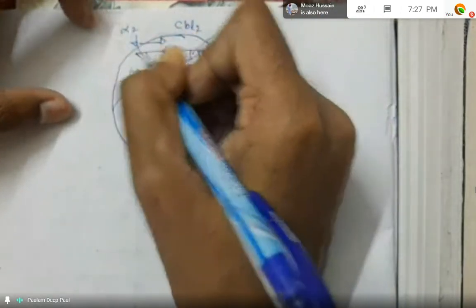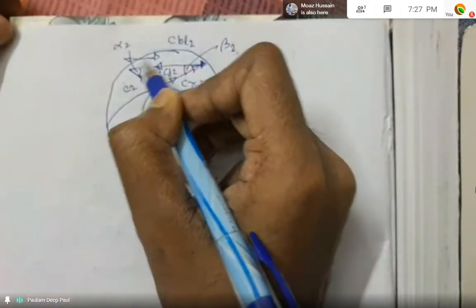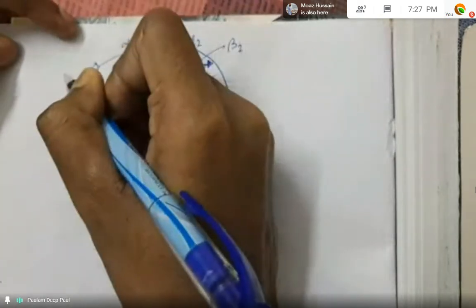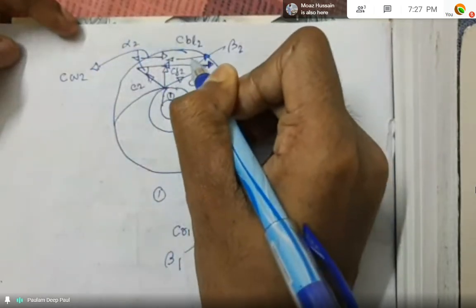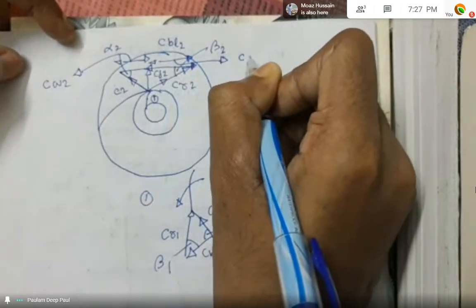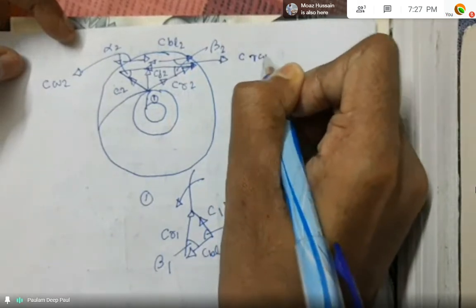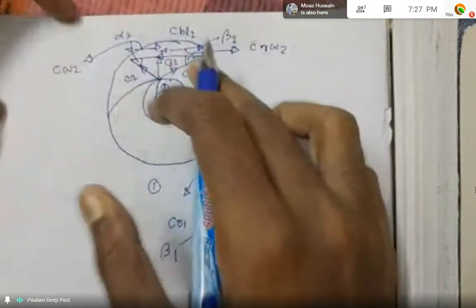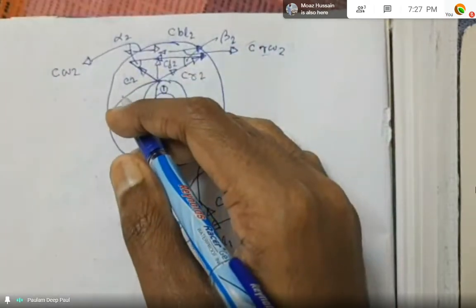So this arrow here will be the absolute whirl component from the absolute velocity, that is CW2, and this portion of the triangle we get a velocity component, which is CRW2, but we won't be needing this that much. Just for the sake, I'm telling you that we get a whirl component from the relative velocity components also.